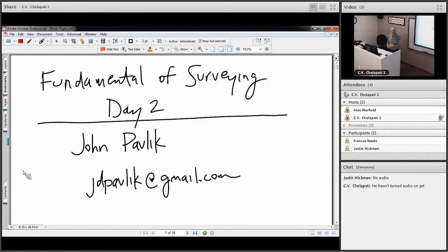We're also going to talk about geodesy. Remember, there's 2 kinds of surveying. Plane surveying, P-L-A-N-E, where we assume the world is flat. And if we're working in a relatively small area, we can do that. But if we're working in a large-scale project, like many times we do, we have to take into consideration the size and the shape of the Earth, and that's called geodetic survey. So we'll learn a little bit about that today. And then we'll finish up talking about mapping, topographic mapping. We'll talk about topographic mapping, doing a conventional survey, using a total station and data collector, and we'll also talk about doing it using photogrammetric methods, all right?